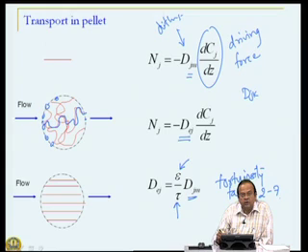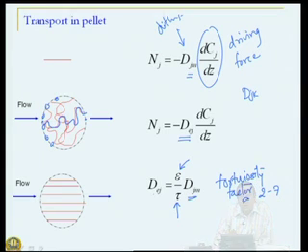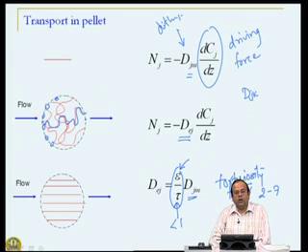So, what it means is that the actual effective diffusion coefficient is lower compared to the bulk diffusion coefficient because of two things: epsilon void fraction which is less than unity and tortuosity factor which is greater than 1. Both these will contribute to this fraction being less than 1, and therefore, the actual diffusion coefficient is something less.